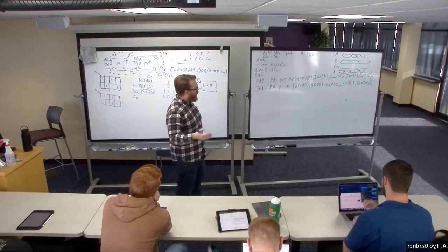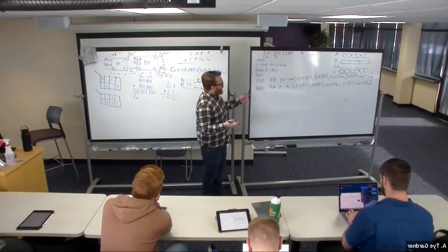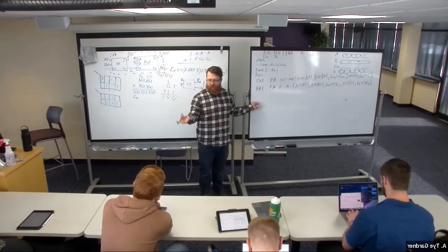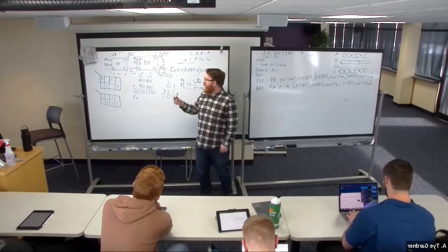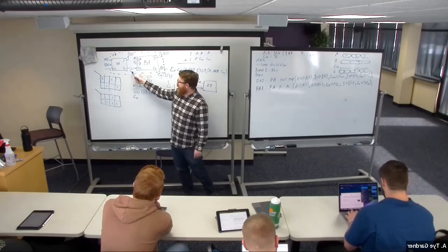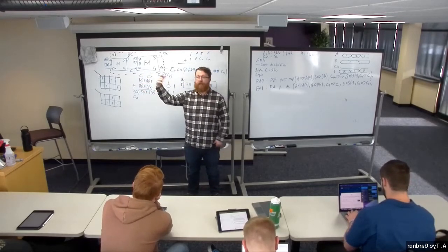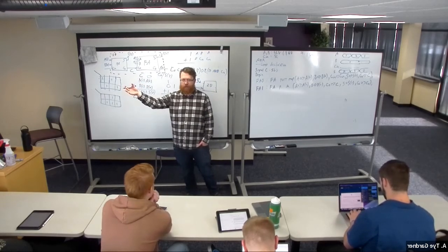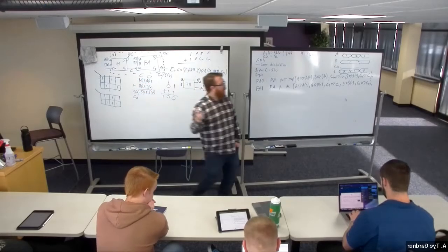Of course, in yours, you have 2 different ways of doing the design for the lab, where the easiest way is I just add another FA2 and FA3 and call it a 4-bit adder, making sure that I have 3 signals that connect between, so I'd have C0, C1, C2 to connect the 3 full adders together, and then I have that final carry out, right? Any questions on that? Okay.